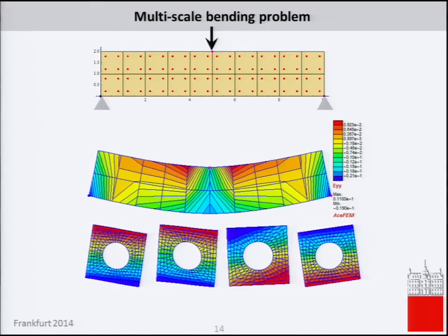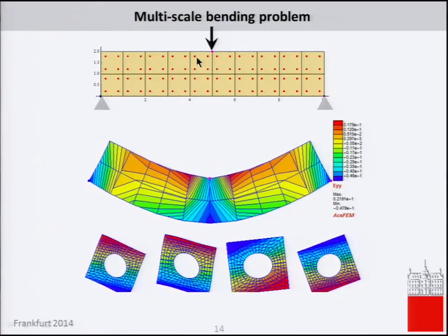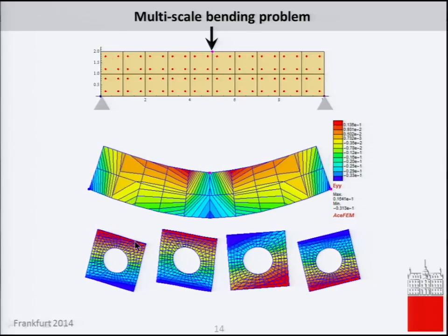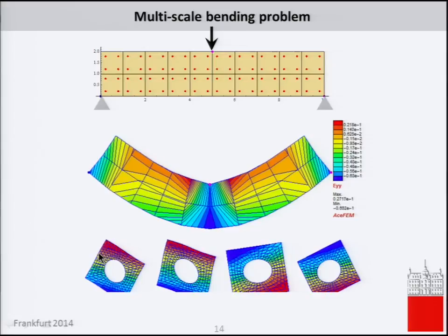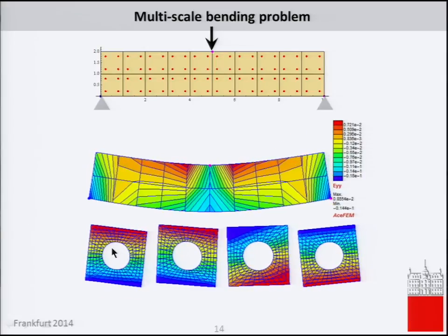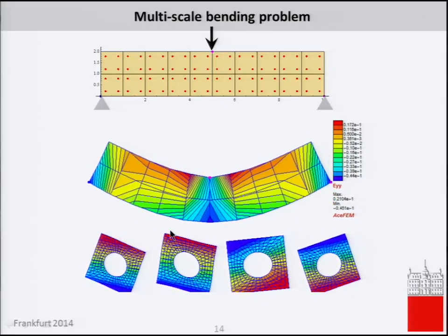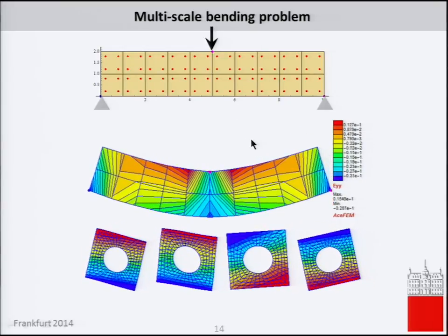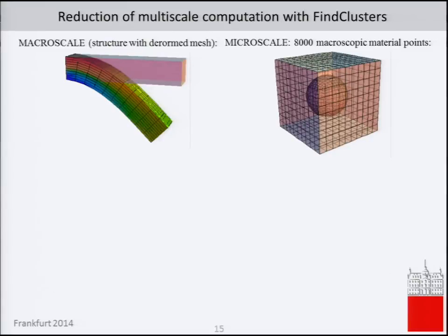Okay, this is an example, pressing down. Each point here, each Gauss point, is independently simulated as a continuum full of holes. So we have this kind of microstructure. We can do this almost in real time for 2D problems, but when we go to 3D problems, there is a problem, because the solution of each nonlinear micro problem is already extremely costly, even for a simple micro scale, like a beam.